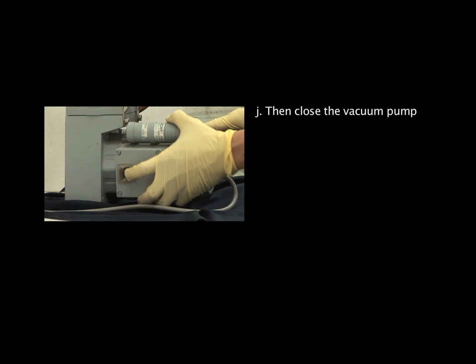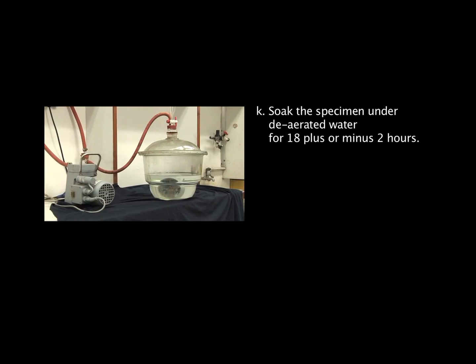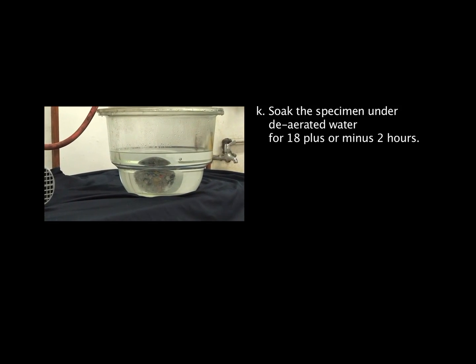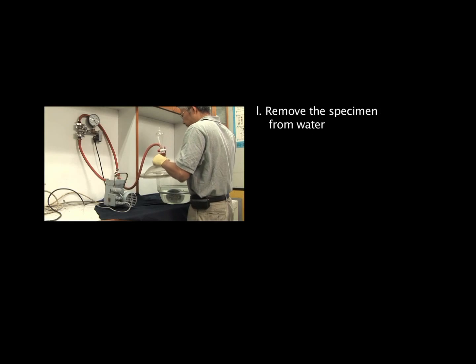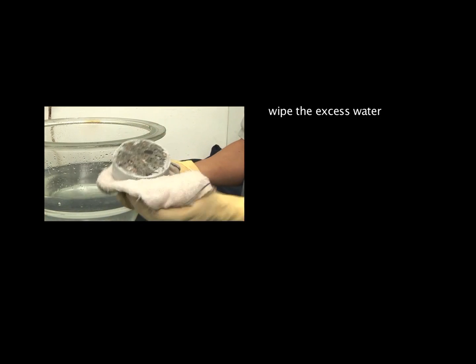J. Then close the vacuum pump. Open the stopcock to let the water flow in, allowing re-entry of air into the desiccator. K. Soak the specimen under deaerated water for 18 plus or minus 2 hours. L. Remove the specimen from water. Wipe the excess water.